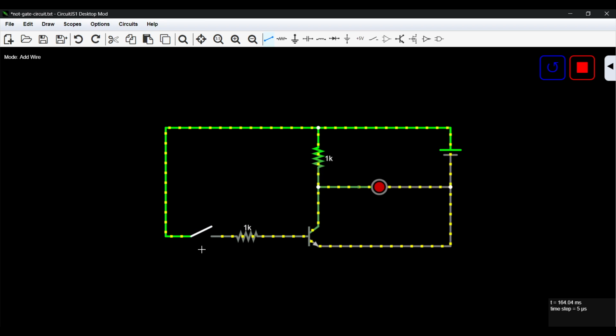You can see that if the circuit is open, as we can follow this green, the base of the transistor over here is not activated. So that means that the current does not flow through this transistor to over here, but it flows over here, and it has an alternative route to light the LED.